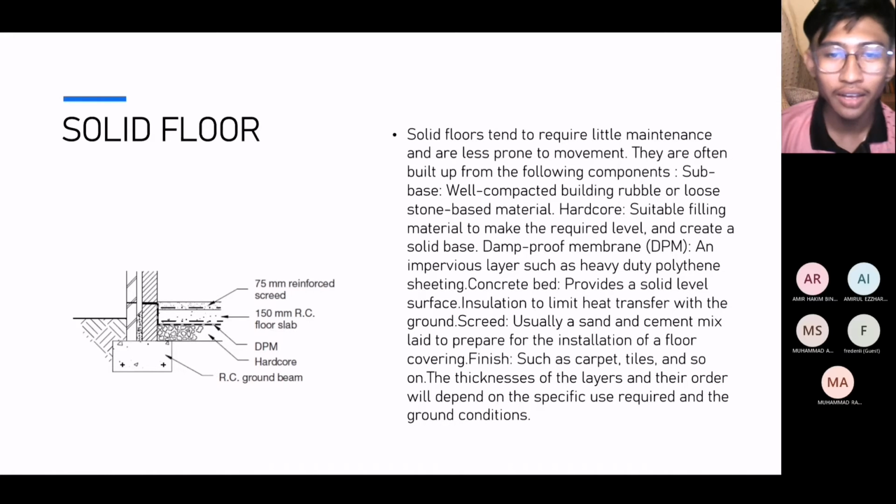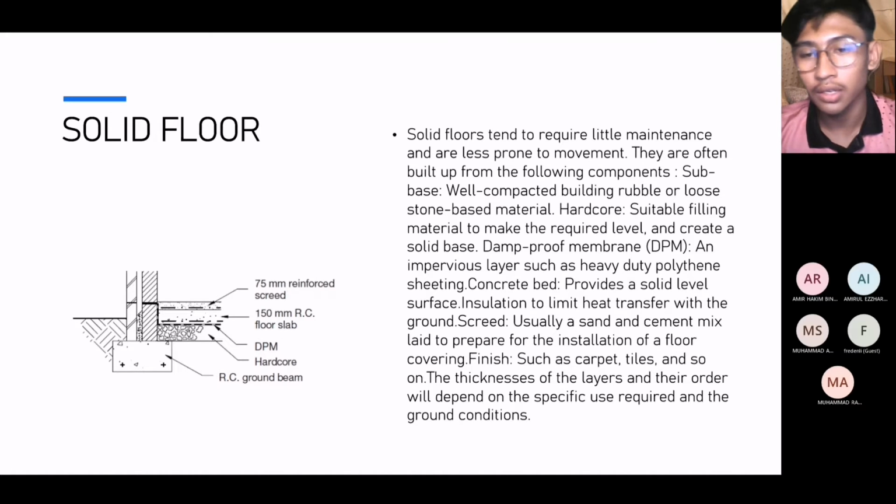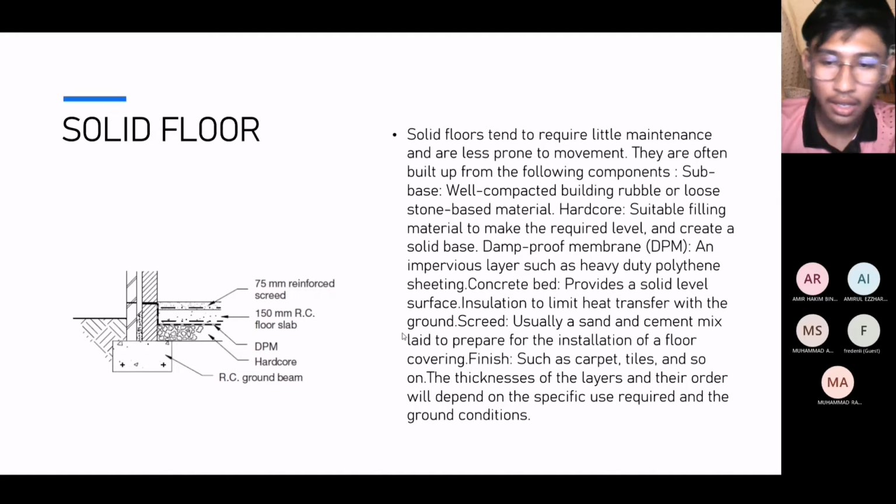They are often built up from the following components: sub-base, well-compacted building rubble or loose stone-based material; hardcore, suitable filling material to make the required level and create a solid base; damp-proof membrane (DPM), impervious layers such as heavy-duty polyethylene sheeting; concrete beds provide a solid level surface, insulation to limit heat transfer with the ground; screed, usually a sand and cement mix laid to prepare for the installation of a floor covering; finish, such as carpet, tiles, and so on.